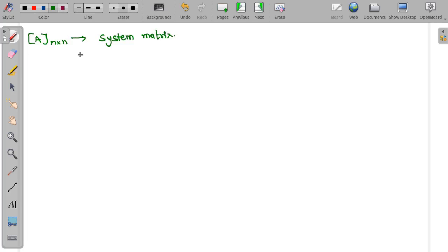And the characteristic equation of the system basically defines all the characteristics of your given system, like your settling time, your maximum peak overshoot. All the parameters are defined by your characteristic equation or the location of the poles, and we can get the poles from the system matrix. So usually your system matrix is always a square matrix.